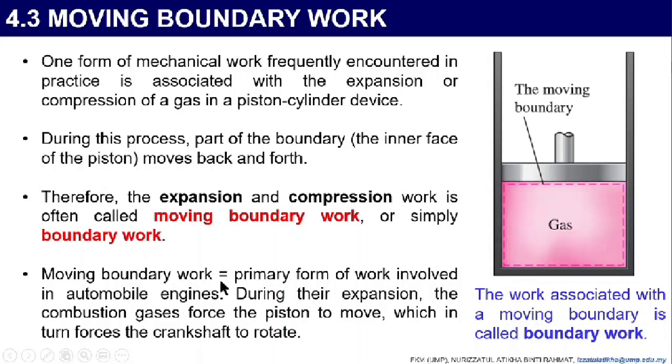Moving boundary work is the primary form of work involved in automobile engines. During their expansion, the combustion gases force the piston to move, which in turn forces the crankshaft to rotate. So maybe you are already familiar with this process inside a car engine, where during the expansion, the combustion gas forces the piston to move, and eventually the crankshaft will rotate.